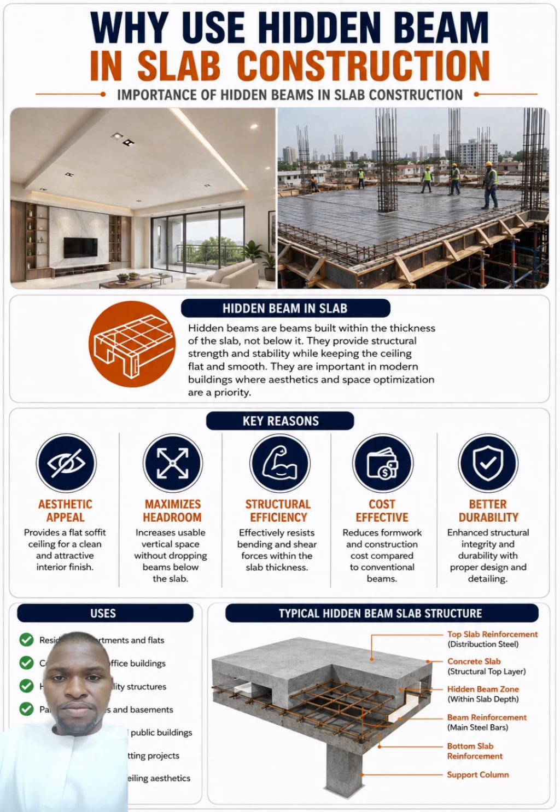So it's cost effective. Then the other point we are looking at is better durability. Hidden beams give that durability to your slab, right? Because sometimes you have a two-way slab with a long span, and you are skeptical whether your beam support is going to hold the weight of the slab.